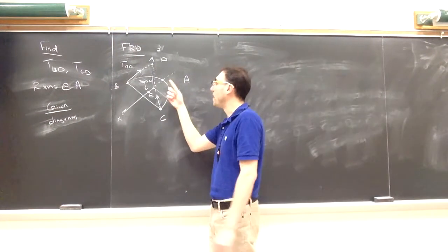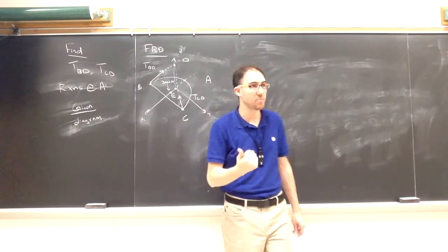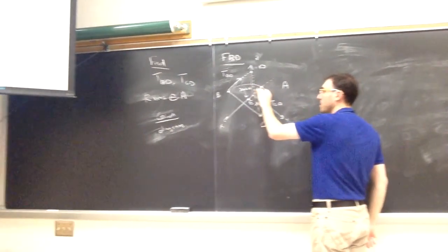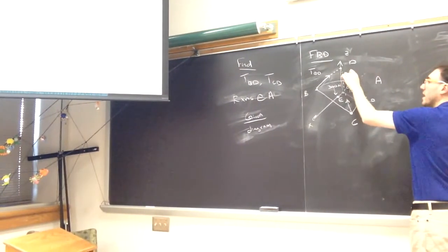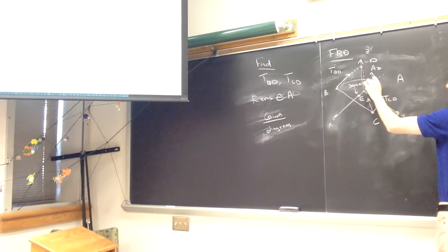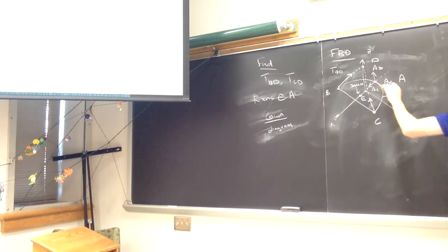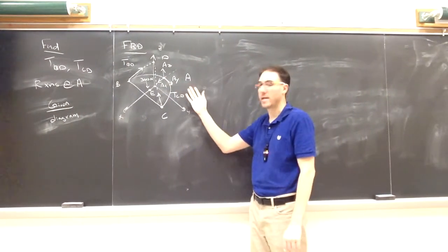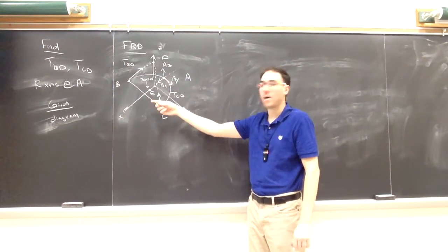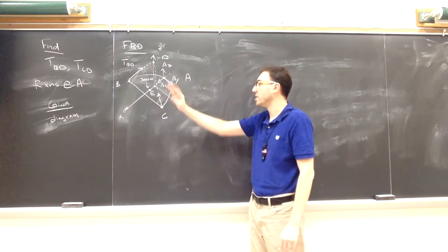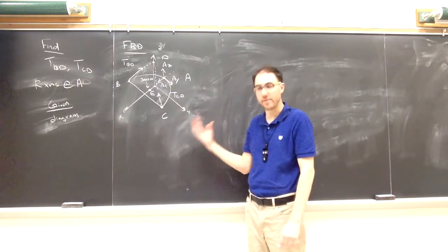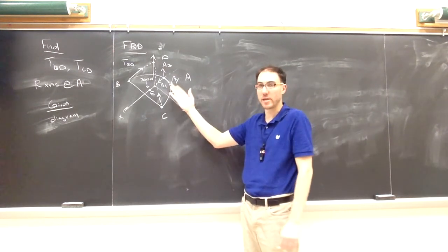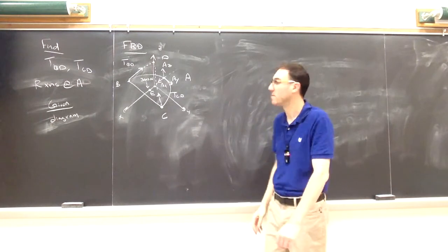So at A, because all the translation is prevented, I'll have a component of force in the X, I'll assume is positive and call it AX. In the Z, I'll call it AZ. And along the Y, and call it AY. I'll reiterate for any of the support reactions that it can't move in or out in the X or the Y or the Z. Just for simplicity and for consistency, I assume they act in the positive direction, and I could turn out to be wrong later.